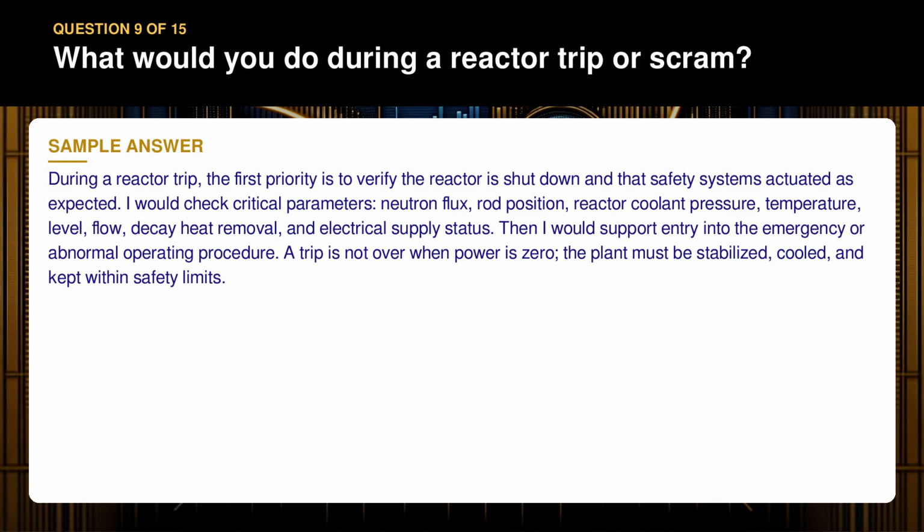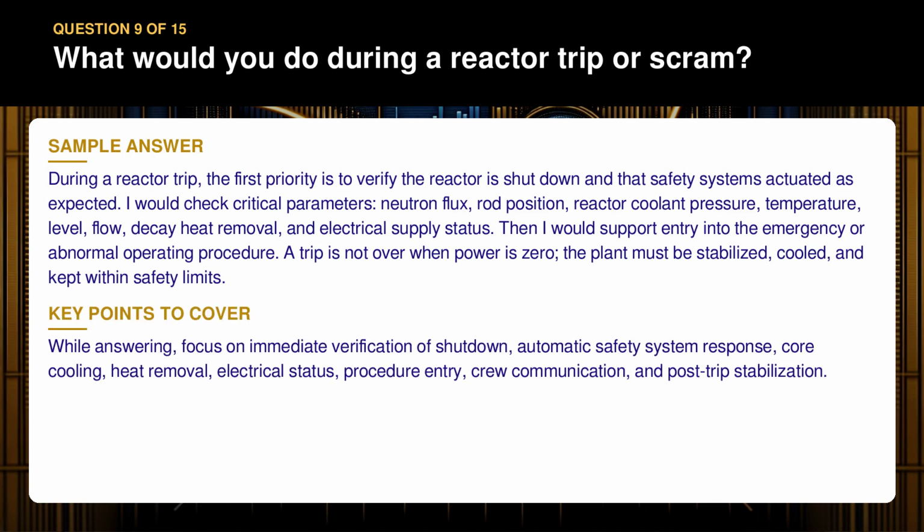A trip is not over when power is zero. The plant must be stabilized, cooled, and kept within safety limits. While answering, focus on immediate verification of shutdown, automatic safety system response, core cooling, heat removal, electrical status, procedure entry, crew communication, and post-trip stabilization.